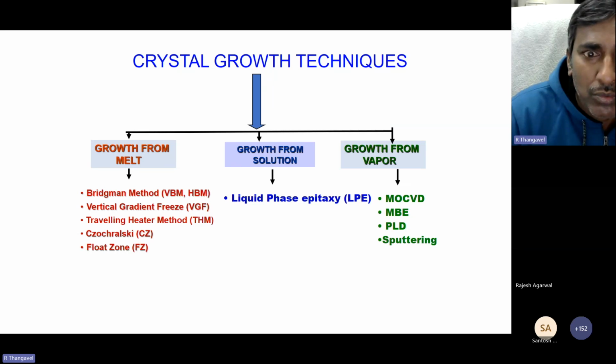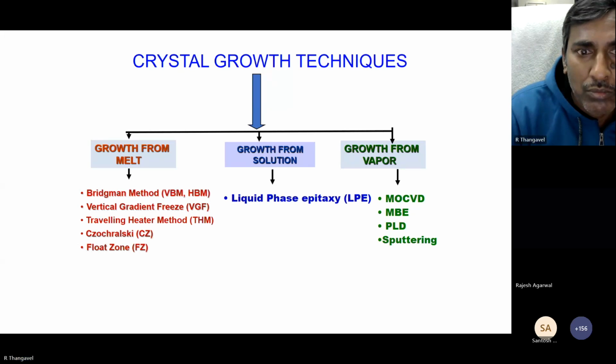Now this is the Czochralski process. This is the silicon Czochralski process. Raw material of polycrystalline silicon has to be kept in the furnace. Then the quartz crucible will be there, and a single crystal silicon seed crystal is inserted below. Then crystal pulling and rotating, these two phenomena are occurring, and there are some parameters. The Czochralski process time should be around 18 to 24 hours, temperature more than 1300 degrees centigrade, pressure 20 torr, pulling 0.7 mm per minute.